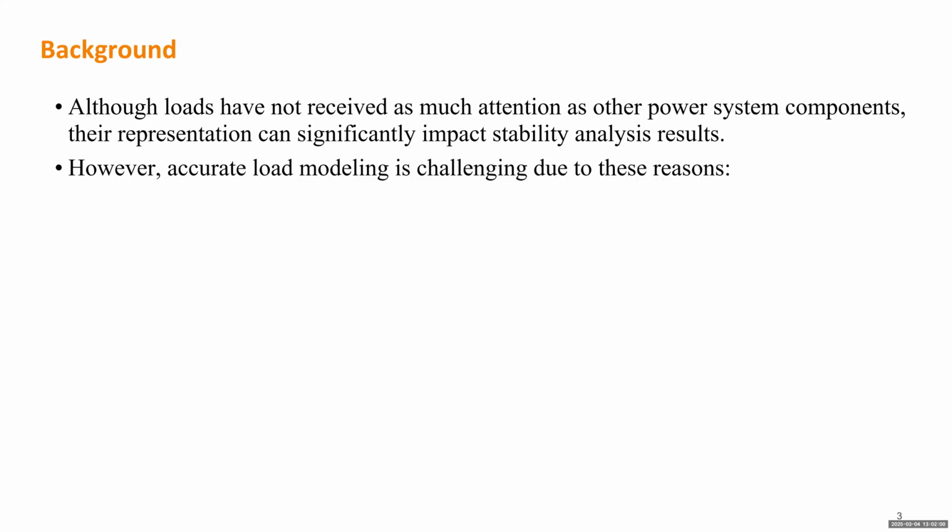But it's challenging to have very accurate load modeling because there are a number of reasons. First, a power system can have a large number of very diverse load components. You can consider each load component as an individual device or even a control system. So if you model every dynamic, every characteristic of that system, it can be very challenging.